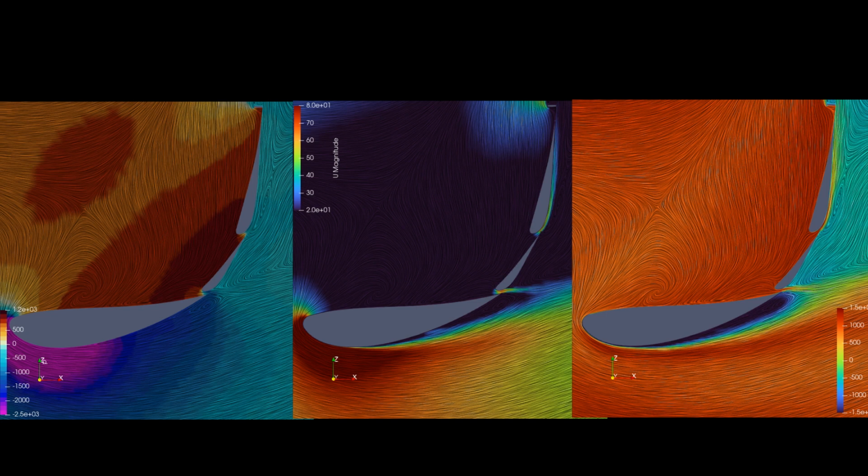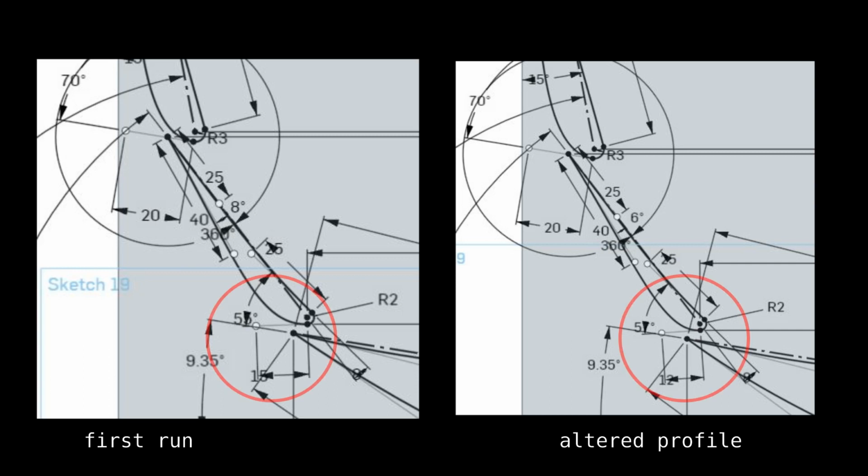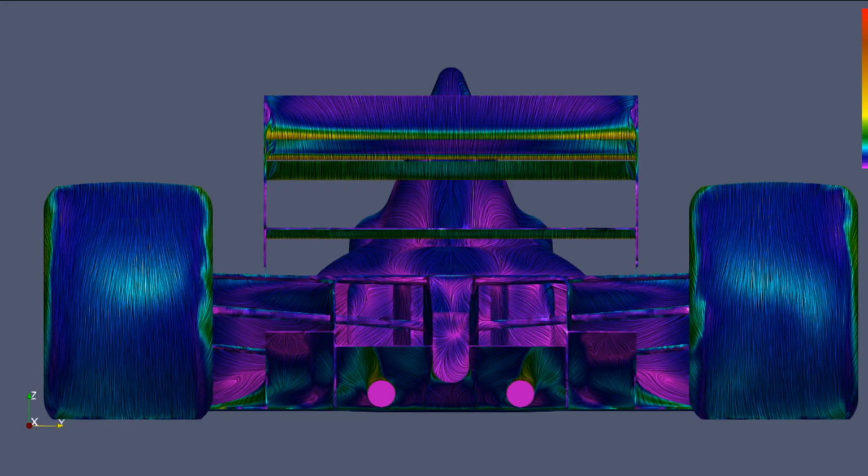Luckily, however, it just seemed the second element wing was the problem, and it was clearly separating in the last part of the curve section. Shortening the length of the curve worked. This gave 1298 newtons, which ended up being a drop of 11% from the wing in the free stream simulations. This is also consistent with the medium wing performance drop. As I said, this wasn't satisfying, but whatever I tried, I couldn't improve on this result.